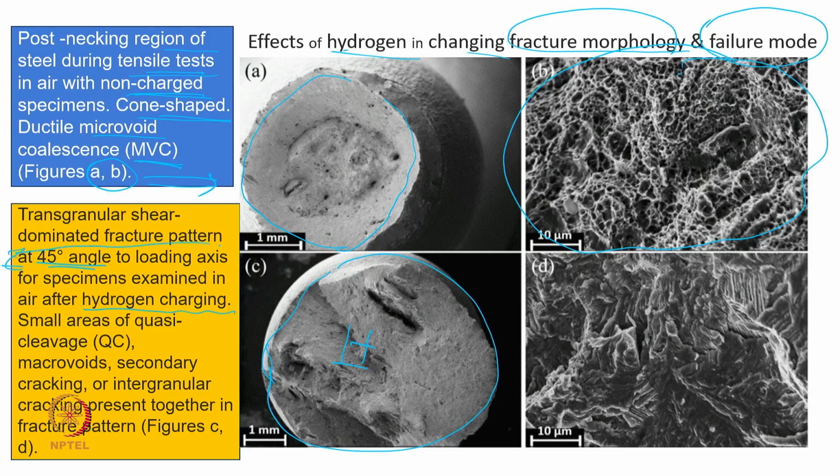However, the failure we see is a kind of shear failure at a 45 degree angle. We are also able to find many more pits, fractures, and elongation of many cracks. So this is a completely brittle failure. Now, when I look at the SEM image, we still find small dimples available, but most of it is a kind of brittle failure.